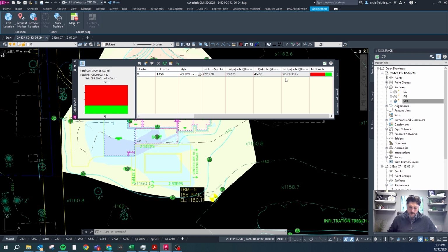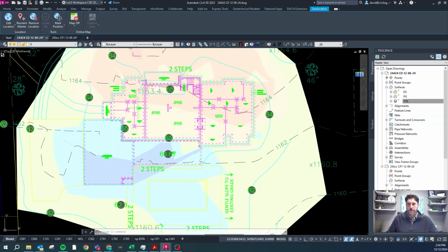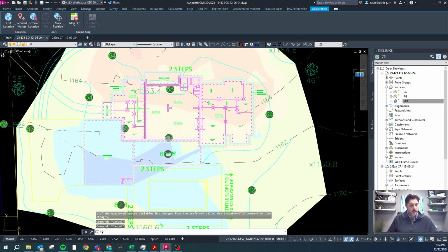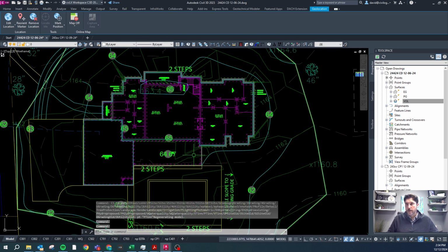And if we do 0.08 acres times 1600, it's 128 yards for the house. If we raise it 1 foot, that's 128 yards. So we need to adjust another probably 2 feet. So we did a little bit of overkill, but part of that really could be some of these funky lines here.